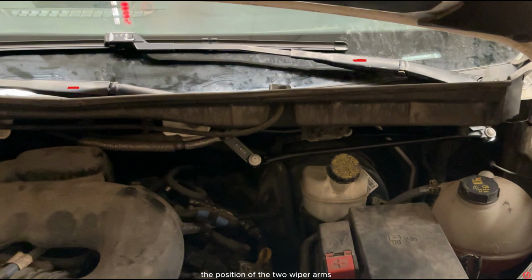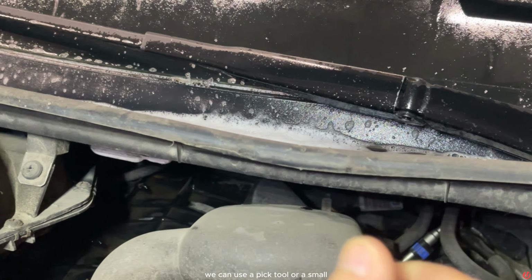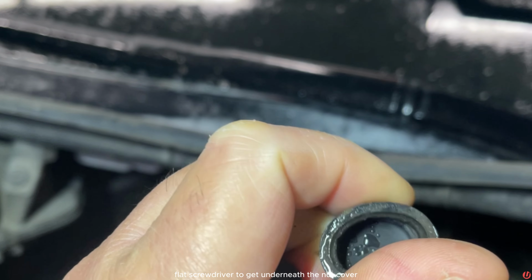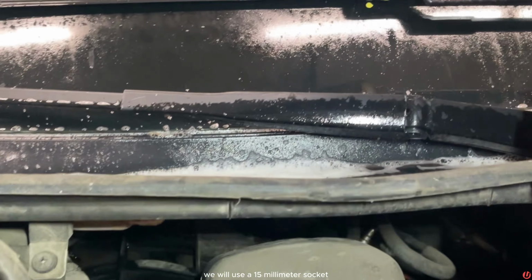Next, we will remove the two nut covers of the wiper arm. One is on the driver's side wiper arm, and the other is on the passenger side wiper arm. We can use a pick tool or a small flat screwdriver to get underneath the nut cover and pry it up. Then we will set them aside. To remove the wiper arm nut, we will use a 15mm socket.